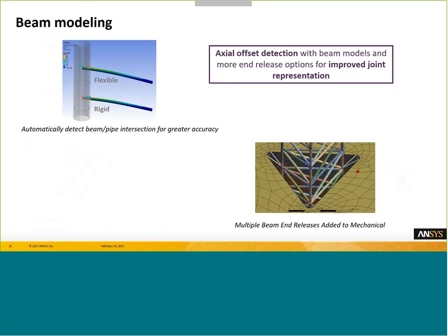Also, we've added in a couple of changes in the way we handle intersections. So on the model on the top left here, if we treat the beam in a standard way, a small beam connected to a large beam, in actual fact what happens on the 3D model is that the beams don't join center to center, they join surface to surface.